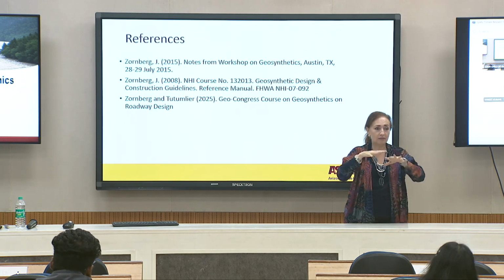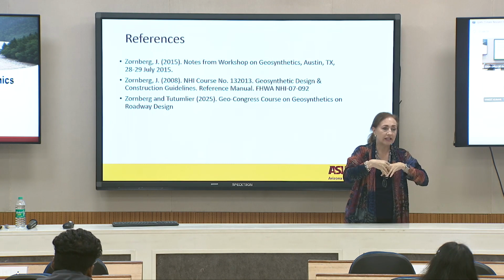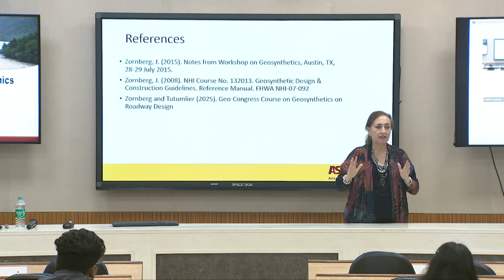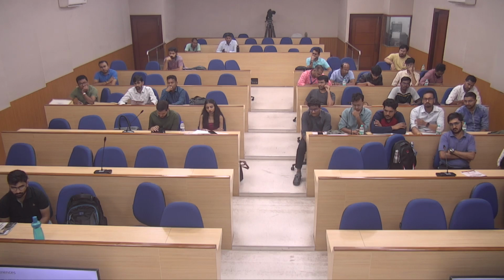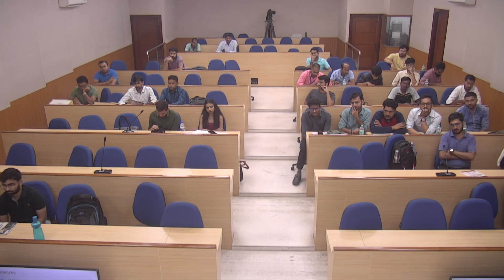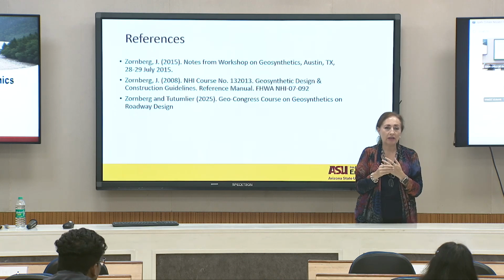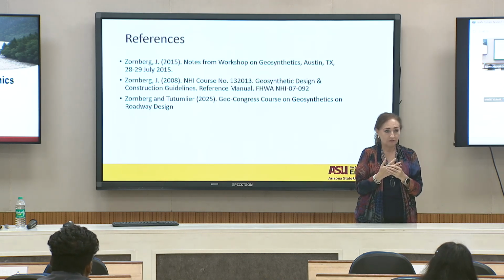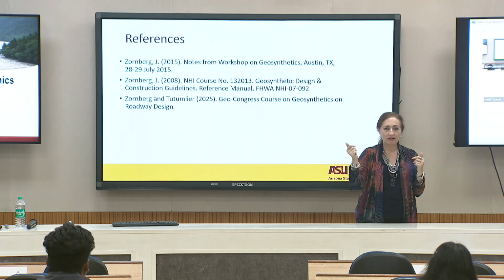Geogrids below the ballast will allow for the interlocking of the particles, and we basically create a way to avoid that spreading. Okay, we're going to see a little bit of the mechanism here, but that is what I understand. It's been working well. Does anybody have any better idea?